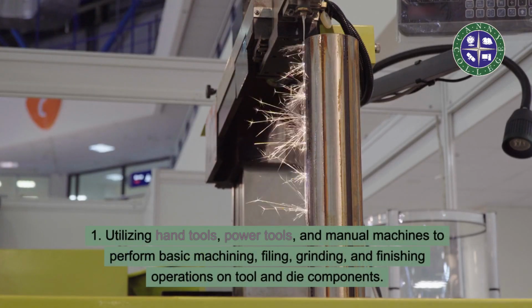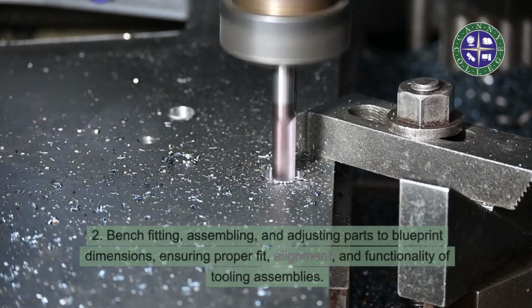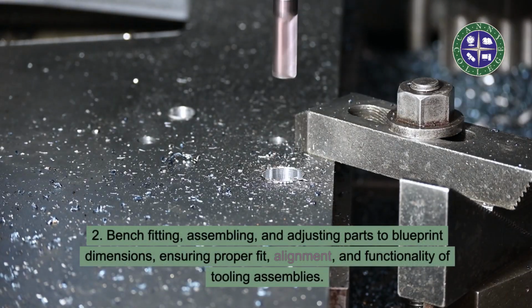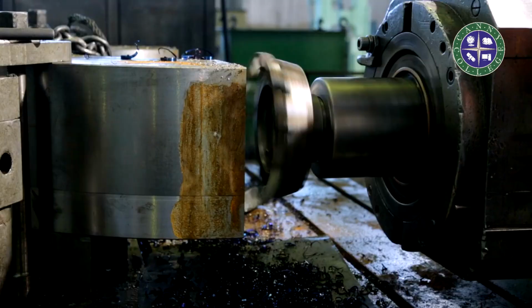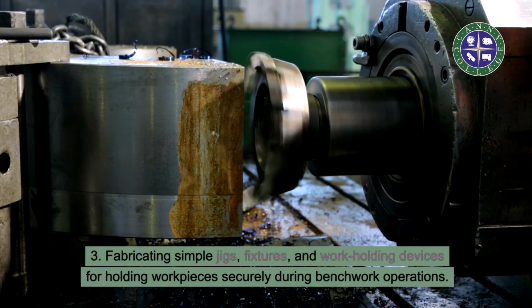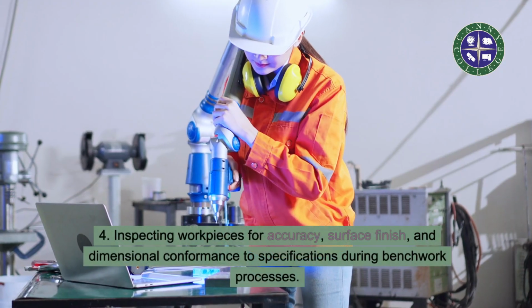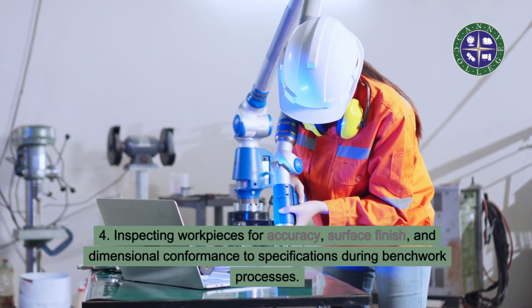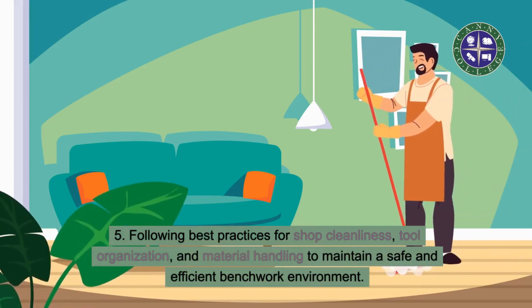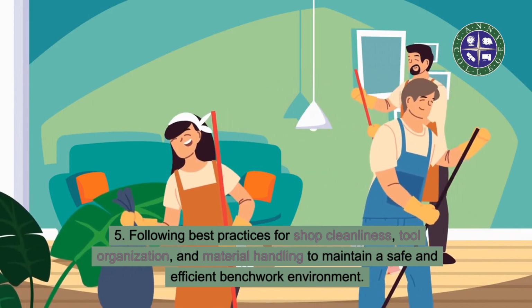1. Utilizing hand tools, power tools, and manual machines to perform basic machining, filing, grinding, and finishing operations on tool and die components. 2. Bench fitting, assembling, and adjusting parts to blueprint dimensions, ensuring proper fit, alignment, and functionality of tooling assemblies. 3. Fabricating simple jigs, fixtures, and work-holding devices for holding workpieces securely during benchwork operations. 4. Inspecting workpieces for accuracy, surface finish, and dimensional conformance to specifications during benchwork processes. 5. Following best practices for shop cleanliness, tool organization, and material handling to maintain a safe and efficient benchwork environment.